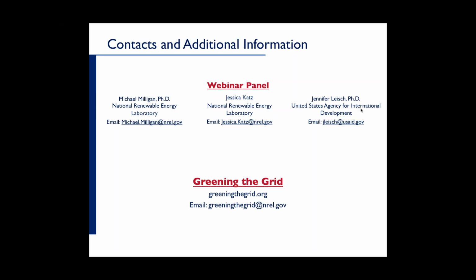When you take a look at the types of flexibility that may be available, it ranges. There are many technologies, for example, reciprocating engines, which are relatively small generators. You get a 10 megawatt engine that ramps from 0 to full output in a matter of 5 or maybe 10 minutes. You could also buy a whole series of these engines, and the ramping capability would scale linearly.